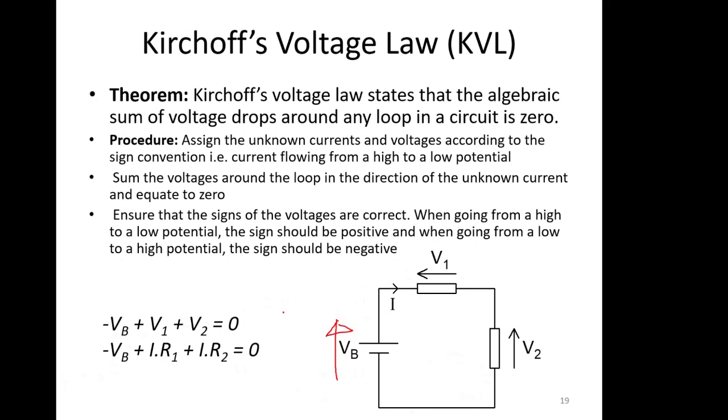Look at that, there's an arrow. So now, having defined that as a positive voltage, you can see that if we add these things around the loop, we've got VB minus V1 minus V2, because we're going against the arrows. We're going with the arrow in this one. All the way around, you could say V2 plus V1 minus VB equals 0, and it just adds up to the same thing. Okay, so it's a straightforward enough idea.